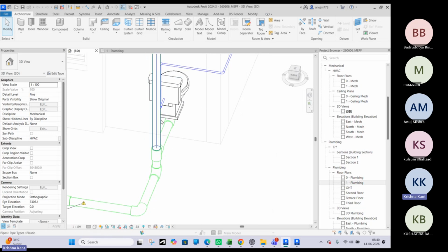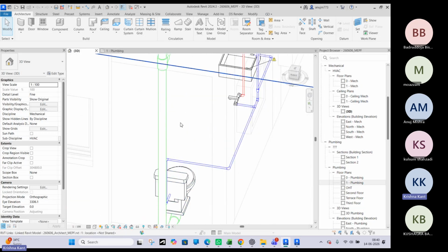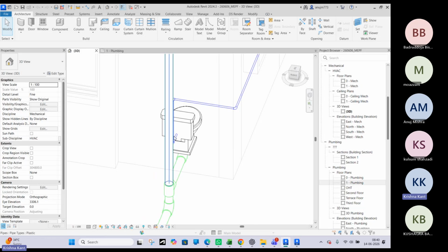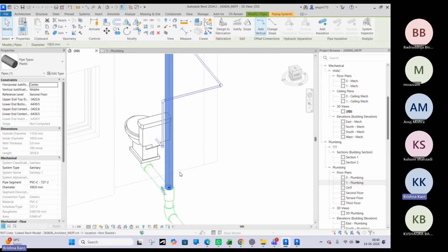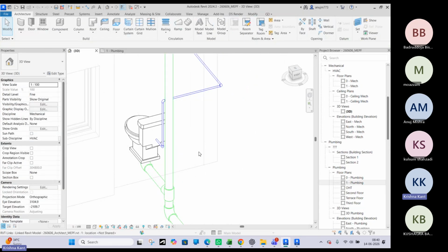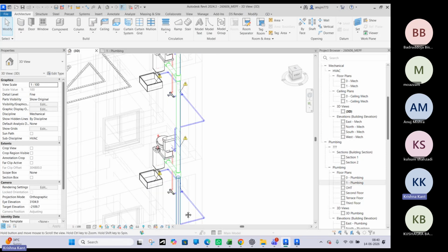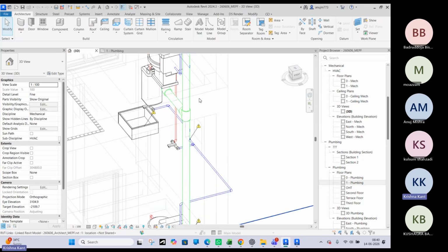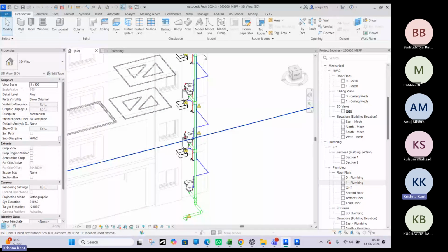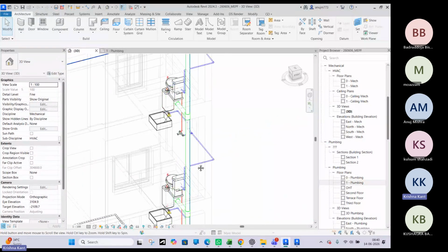As per a standard, we have to bring it outside with two separate pipes. But in some small housing, we just connect our pipe to this pipe only. We will not provide a separate pipe unit for the floor drain trap.